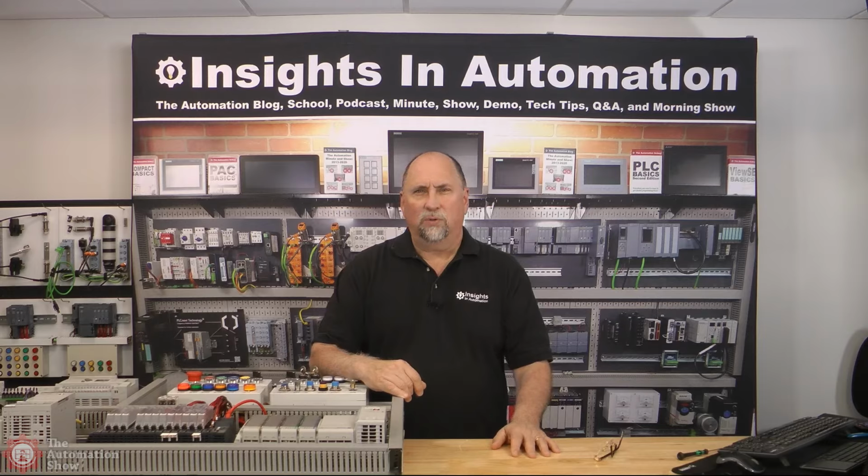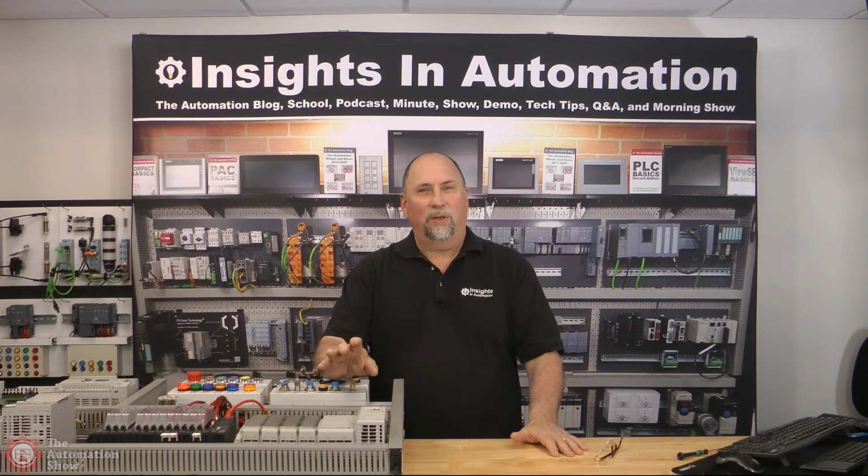And as far as bringing that EDS file into Studio 5000, that seemed very intuitive, right? And so I think a lot of people are using that feature, but they're not promoting it. But by saving that EDS file out of the configurator and bringing it into Studio 5000, everything was laid out. The biggest thing I think is I would love to see the configurator describe each of those points. Wouldn't that be cool?